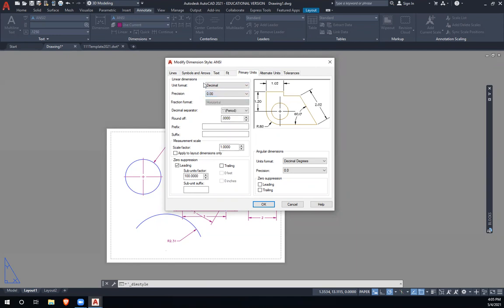2 decimal places is the standard precision for any dimensions that are greater than an inch. Anything bigger than an inch gets 2. Some dimensions that go smaller, like 1/2 an inch or whatever, they use 3. AutoCAD has no accommodation for that kind of rule, so we can leave it at 2 because most parts that we draw are bigger than an inch. And the parts that aren't, you can just right-click them and change the precision, so that avoids too much clicking.